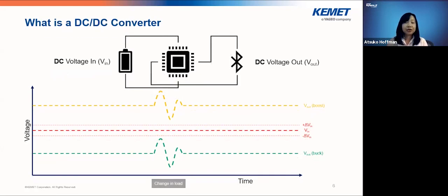In addition to generating output voltage, a good DC to DC converter maintains a stable output when the load current changes. It also should have a good transient response that can minimize settling time, overshoot and undershoot of the output waveform when there is a sudden fluctuation on the load.